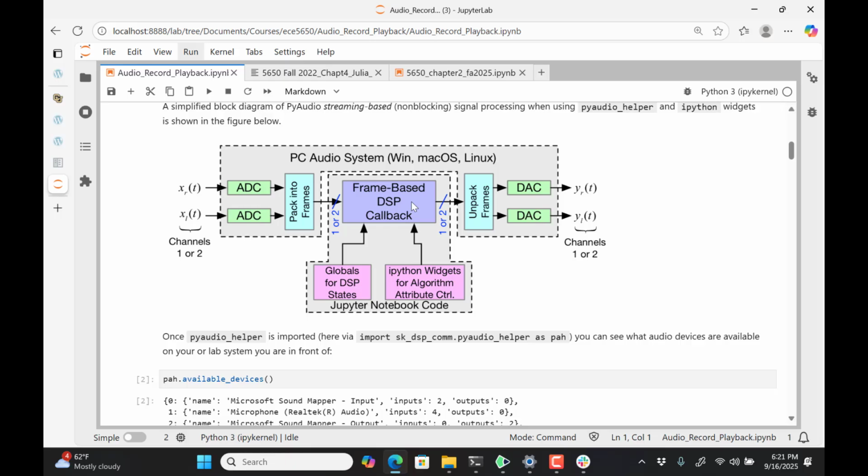But a long frame leads to very long latency. And what that means is if you're speaking into a microphone and listening to the back end of this thing, you will be annoyed by the latency of about a quarter to a half a second. It's very bad. It's just the nature of the PC audio system. If you listen to music, you never notice that latency because you only hear something. If you were to put live stuff in, you would notice there's a lot of latency. So this system is very powerful, but it does have a large amount of latency.